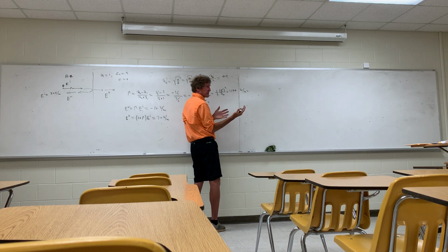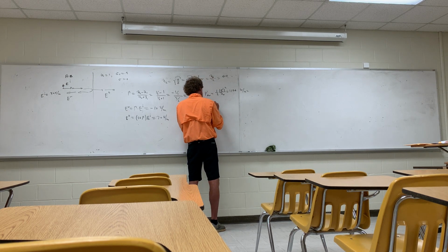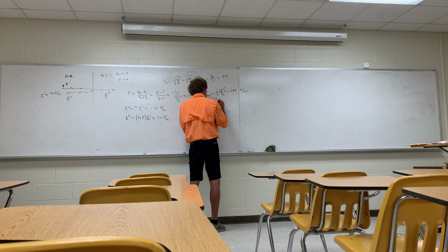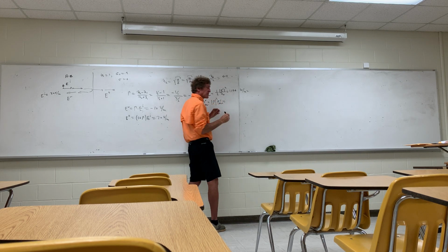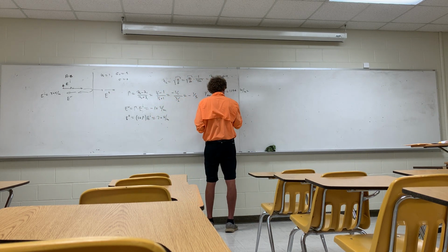The reflected power, the average density of the reflected power, you can get a couple ways. You can find the reflected field strength, put it in there, square it, do the same thing, or you can just take simply the magnitude reflection coefficient squared times the average power density. It's instant, and you'll get it. And can you give that to me? Either one will work. 0.1329.